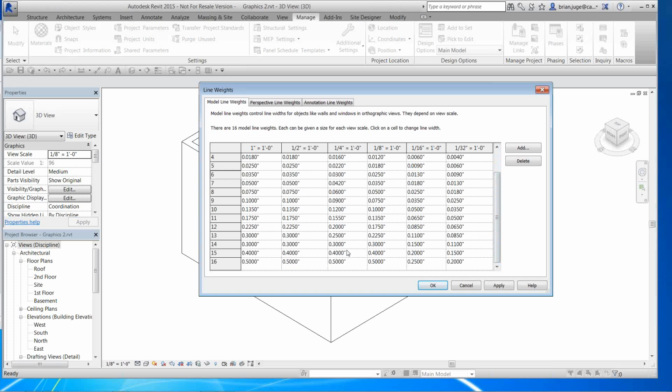And we have a really good comment from Mario for everybody to keep in mind as they're working with this and starting to use it. Mario mentions it is prudent to do a test plot with different drivers, PDF, etc., to make sure that all the line settings are actually useful. Sometimes, as he comments, you don't need 15 different lines when only 5 really read when printed. So keep that in mind.